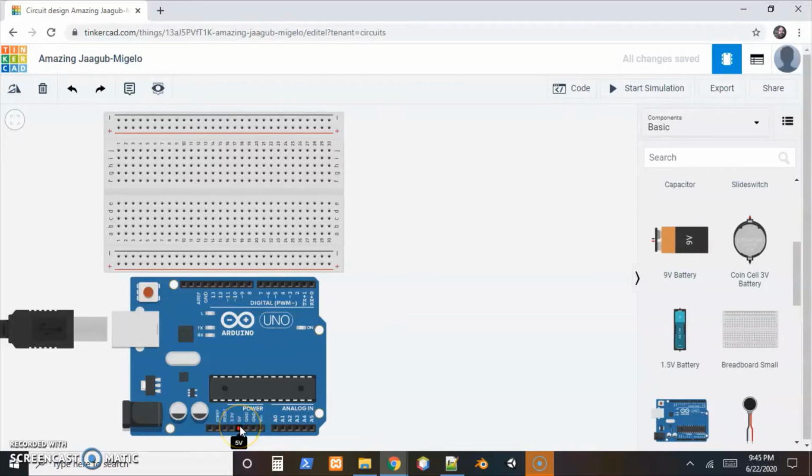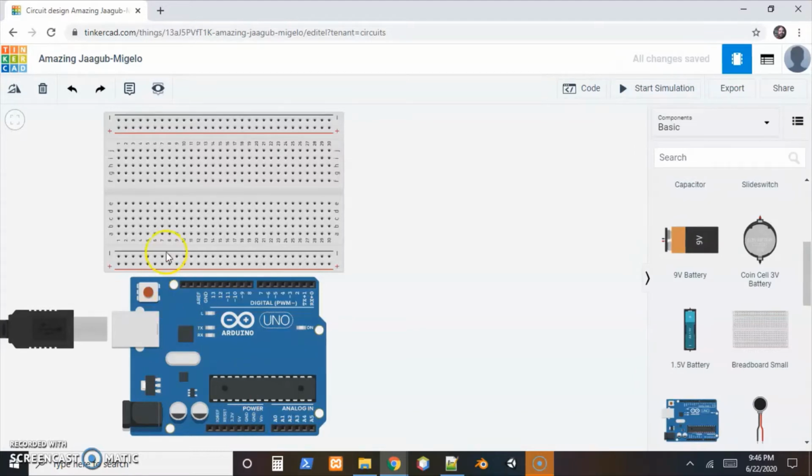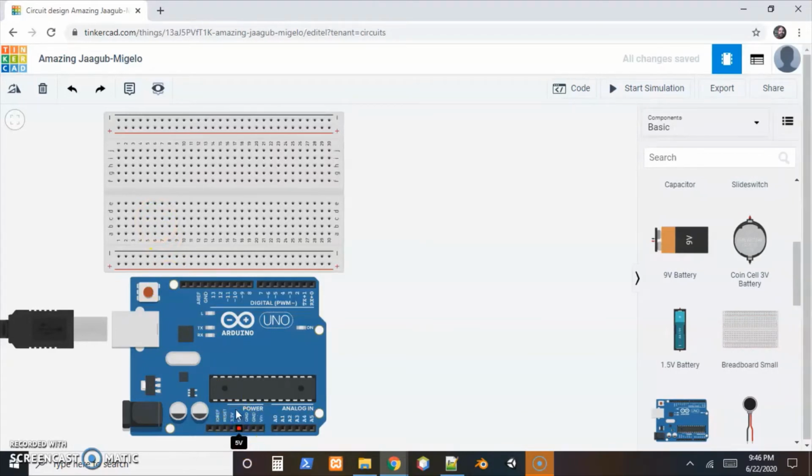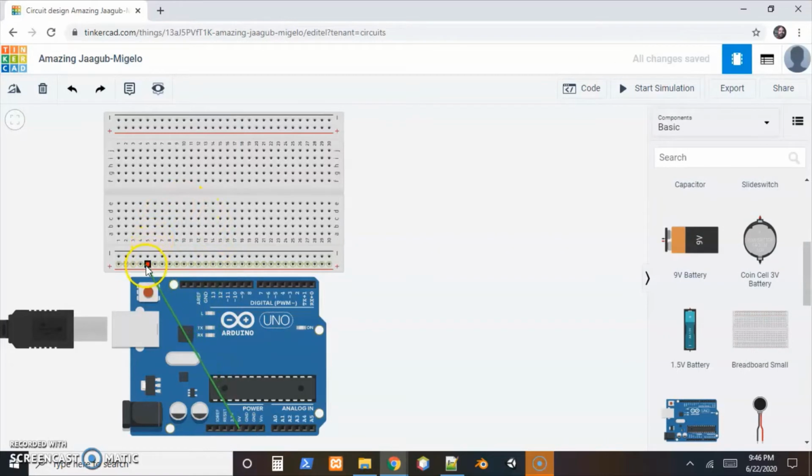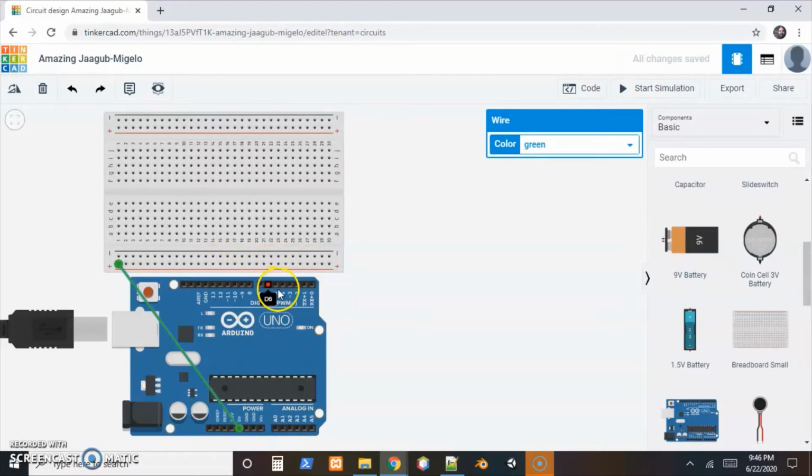So we'll have the 5 volts of electricity come out of this pin over to our breadboard. I'll go ahead and draw that line. We click on that, bring the mouse up here, and click on where we want it to go. I'll make this positive labeled rail the source rail. So now all of these will have 5 volts when we need it. And when I said high voltage, that's what the digital pins send. If we say write that high, that sends 5 volts.